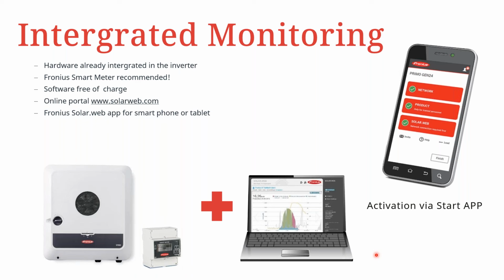It is also possible to first have this system monitored by your smart device, that is your phone, and it is also possible to use your commissioning app, which is the Fronius Solar.start app. With it, you can not only install or commission your product, you can also, through the Solar.start app, have access to the system and register this inverter or these inverters, if they're multiple, to SolarWeb.